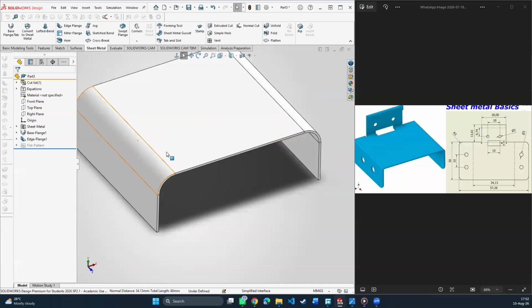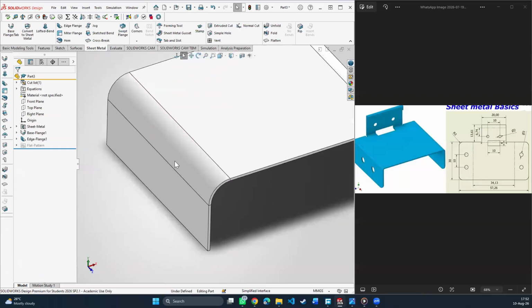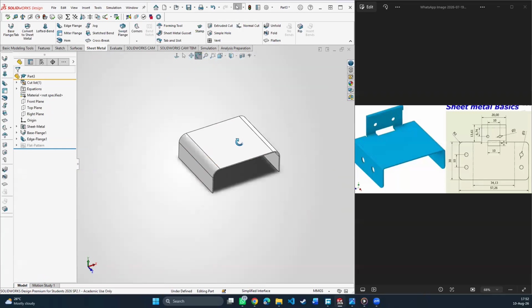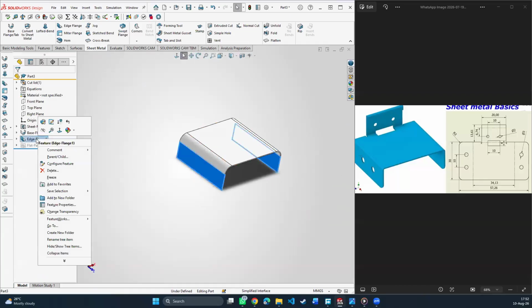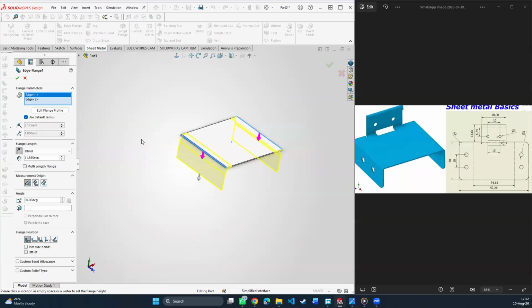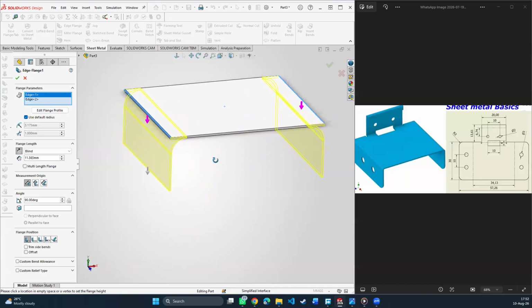If you click on OK, you notice that the bend I'm getting is a bit too much by the time you look at the drawing. So we're going to adjust it. Click on edit feature. Usually for standard exams, they're always going to tell you the bend to use. Normally you're meant to just use your default bend unless they specifically tell you to change it.